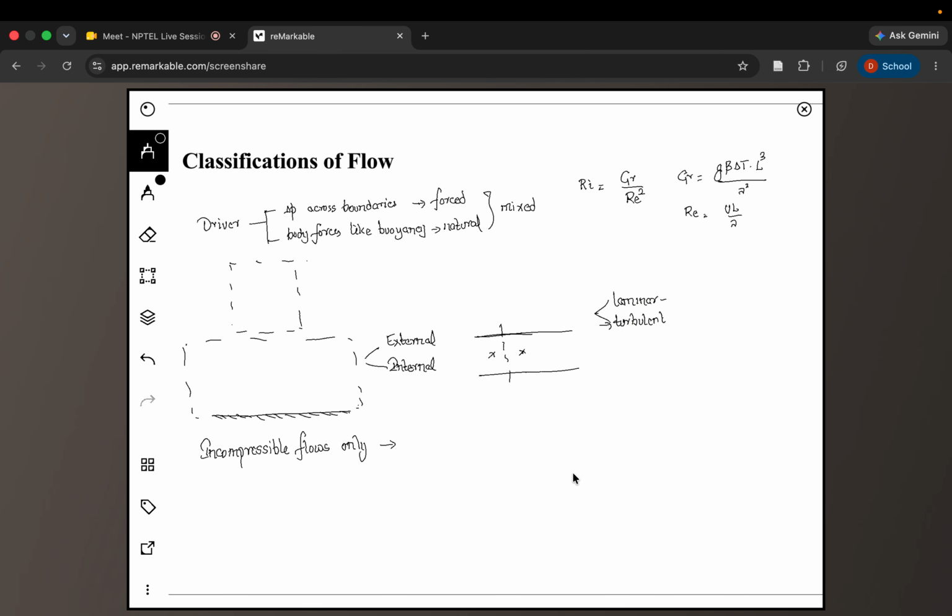Otherwise, for now it will be fairly easy to understand. In simple words, in a laminar flow, you will have a layer-like structure to the flow, where if you put some probe somewhere inside the flow and try to measure the velocity, you would not find any random spurts of noise if your measurement system is good enough. But in a turbulent one, we would be seeing some kind of oscillations around. Say if I were measuring at some particular point in a laminar flow, there could be unsteadiness, but there would not be complete randomness at that particular point. But if I were seeing turbulent, I would see some kind of burst around that. How do we quantify this burst, and how do we do some kind of averaging to remove this, and how do we treat unsteady flow, and all of that we will discuss in week 11.